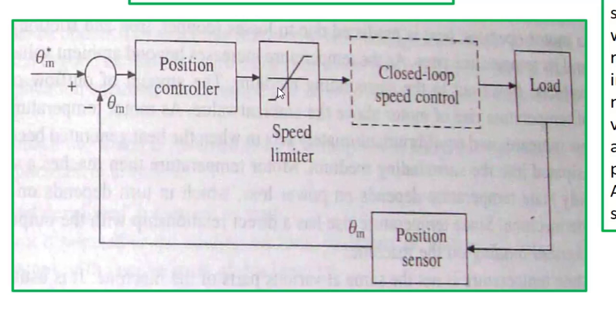Beyond this range of speed it will saturate, and in the negative direction it will also saturate. When it saturates, it will generate a reference signal for the closed loop speed control. It is nothing but an inner current control loop, already discussed in earlier classes. Here the speed limiter will generate a reference current that will be the maximum allowable current flowing through the converter and motor.